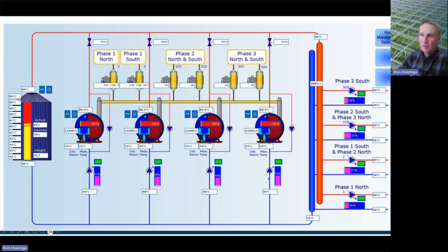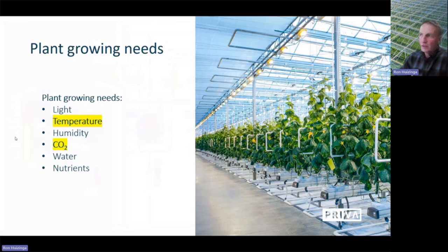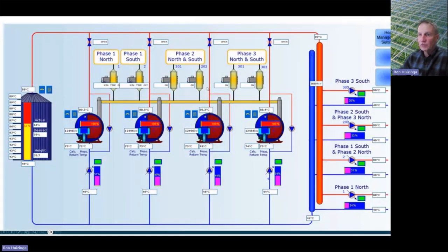Let me say something about that for a minute. As that 90 degree water comes in, it's pushing the coldish water out. These tanks layer really well. You can see that we get 90, and all these temperatures are within a couple of degrees, and then all of a sudden it drops from 83 to 43, and these ones are all within a degree. This is pretty typical of tanks; they should layer very well. If it's not layering well, then there's typically something wrong in your tank.